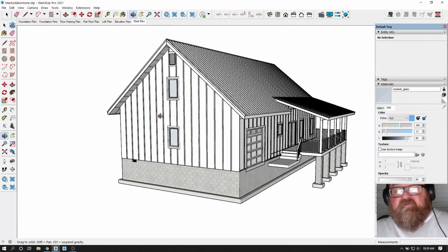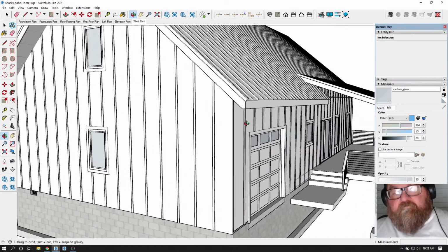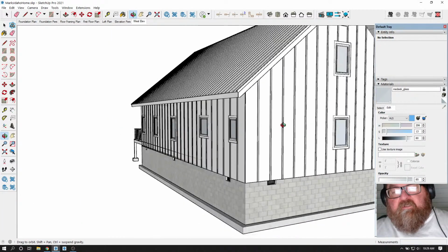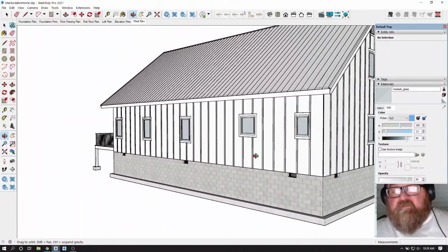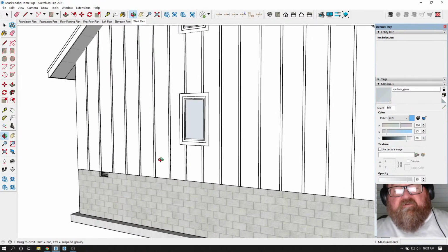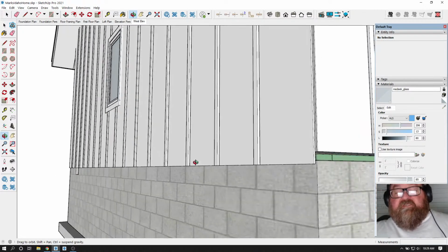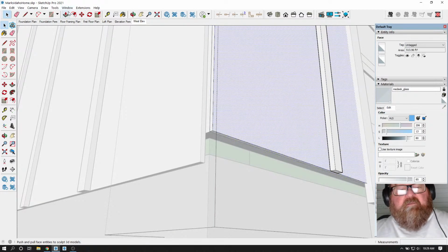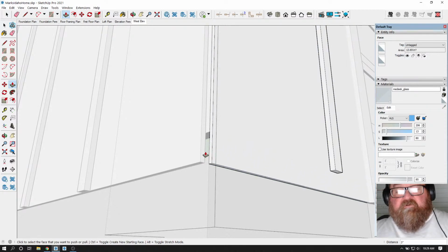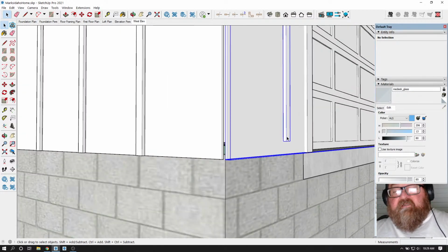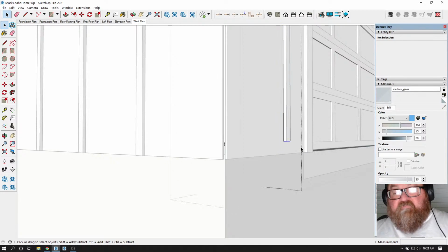So what I need to do is figure out what we might have to do. I need to talk to Mark about this. If he wants a band around here, if you want to save some money, the budget way to do this is to let your siding come down and hang down an inch past your bottom plate. Oh, by the way, I'm gonna fix this. And of course I got to put corner boards on, so that's why the corner's still exposed like that. But that's the most affordable way to do it.